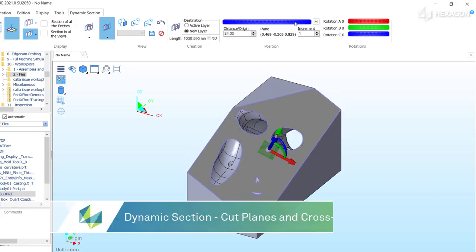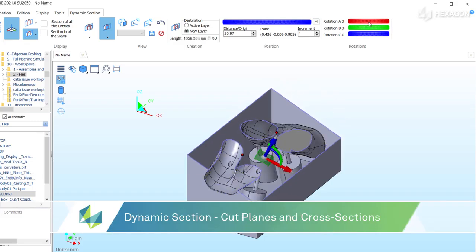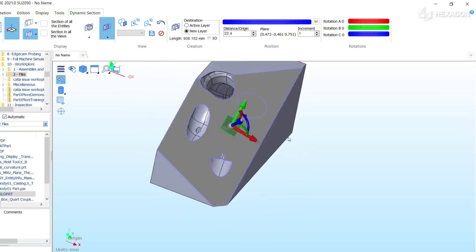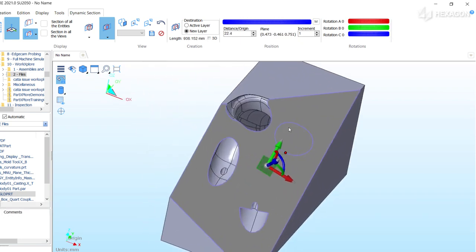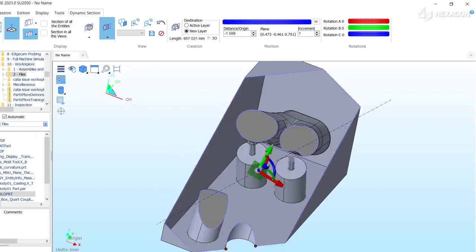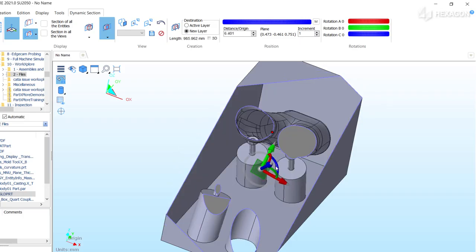High-performance dynamic sectioning allows users to control the section plane with the mouse or the dialog menu in rotational and panning directions. Grabbing the orbit or the axis marker, the user can push or pull the vector to dynamically section the solid model.